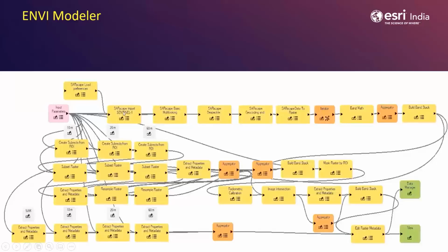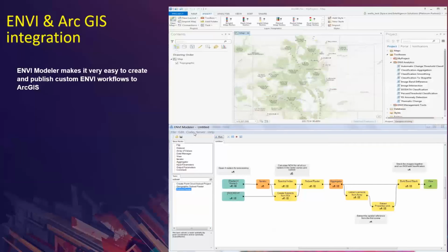For a small area, I've already created a DSM. This is the terrain model wherein I've extracted the buildings and trees. Depending on the parameter that I've given, it has identified even the trees that have a minimum height of, say, 5 to 10 meters.